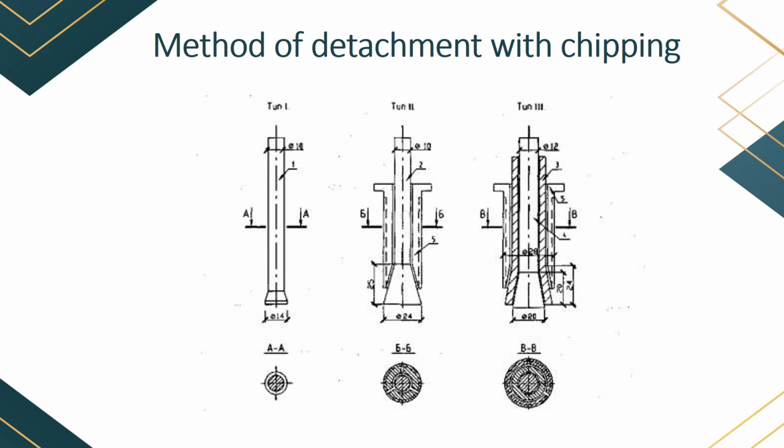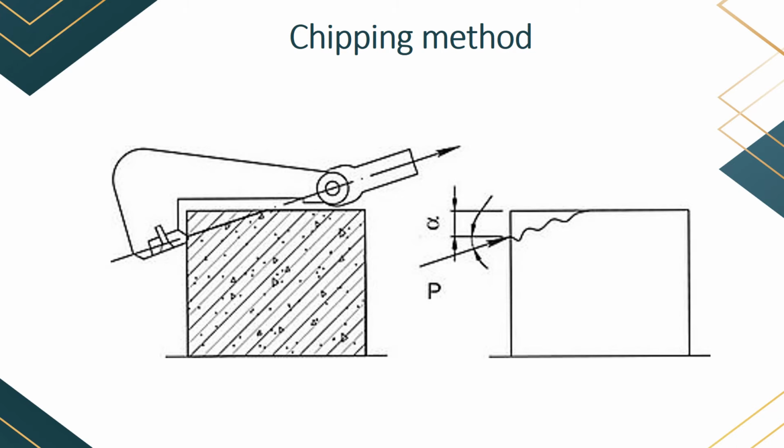During mechanical action, the anchor is tensioned inside the structure, which pulls its part. The monitoring device records an increase in applied force. The process continues until the device shows a sharp decrease in the pull-off force, which will mean a partial destruction of the structural material in the anchor attachment area. Chipping a rib is the third method of local destruction.